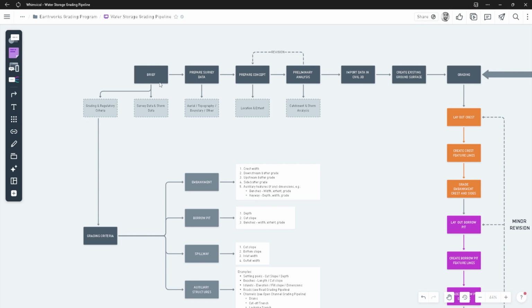And what our job is to bring that design to life, because it's usually just a two-dimensional picture. It really doesn't have any meaning beyond pointing out a certain location and the extent of certain features. It's just a two-dimensional extent. The goal of grading is to embed those two dimensions with another dimension, which is volumetrics.